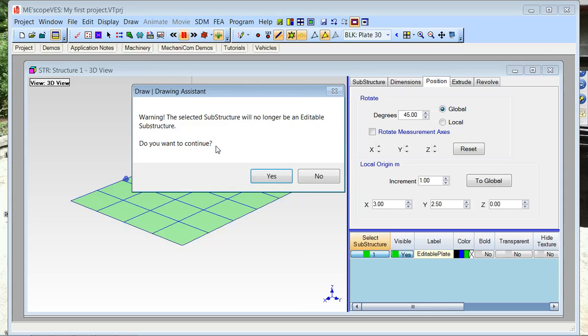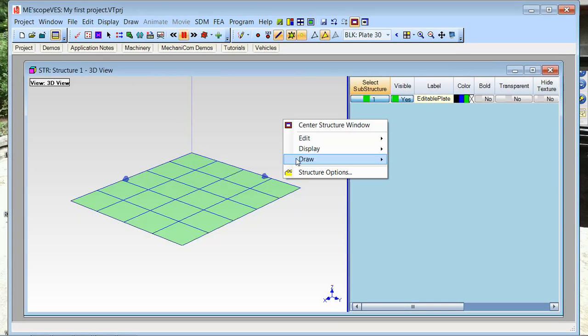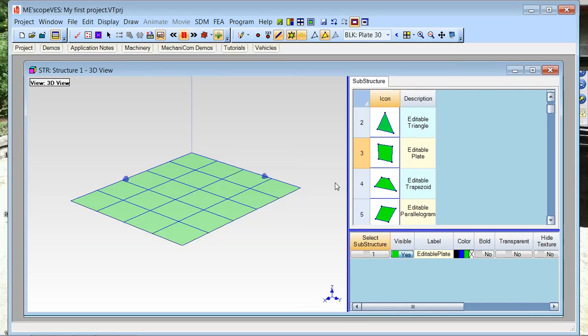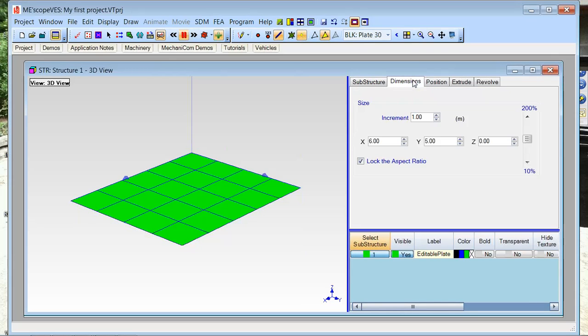Well, that is in another place, and I need to go down here because we're going to create animation equations. And we're going to do that by assigning measurements from the data block to points and directions on the model. So let me open up the equation editor. We don't have any equations yet, but I need to define not only the points, but the direction of measurement in which I took this data.